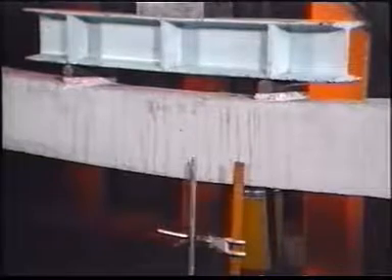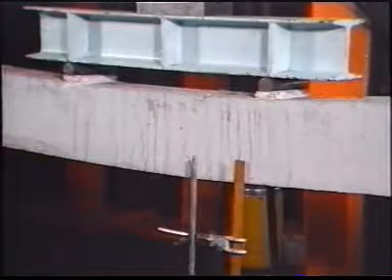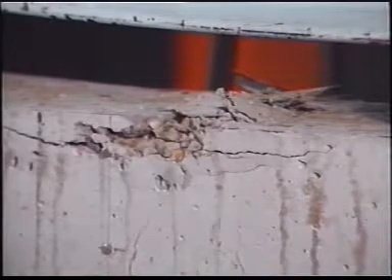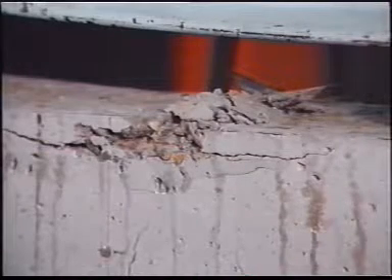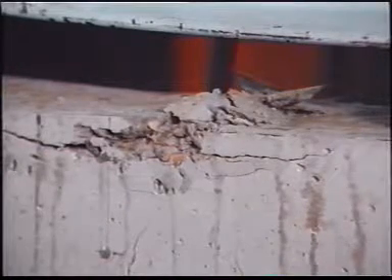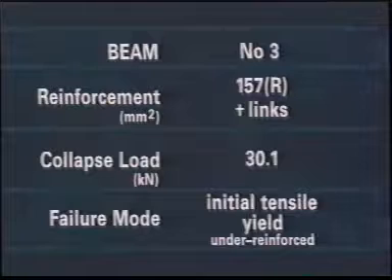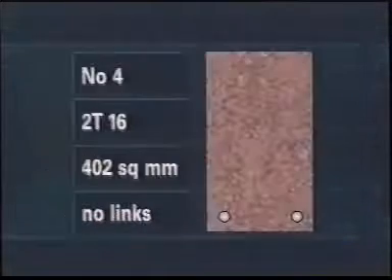Deflection is enough to warrant removing the gauge before failure occurs, although this is most in evidence at the top of the beam, in the failure of the concrete in compression. From now on, this is where all the failures will show themselves finally, unless the beam has no links.